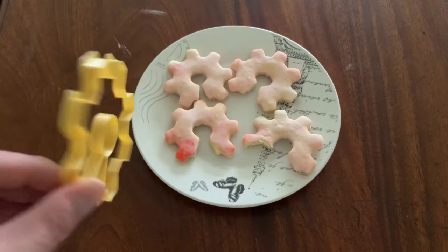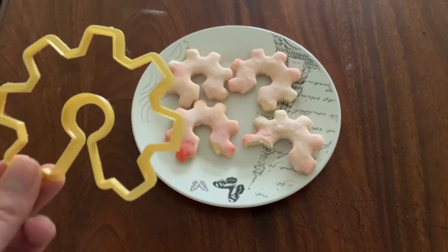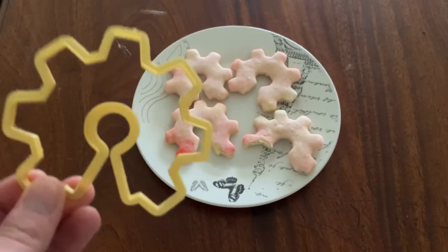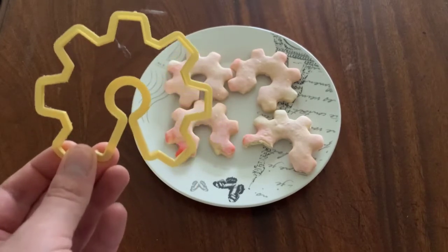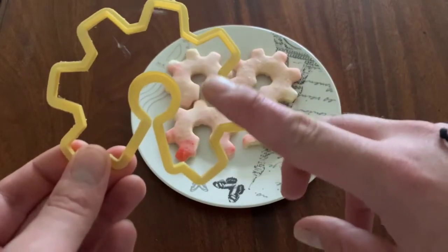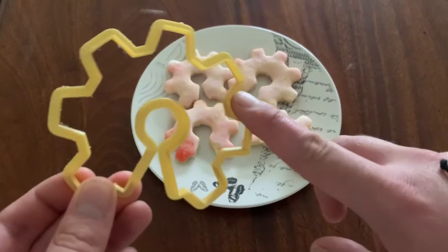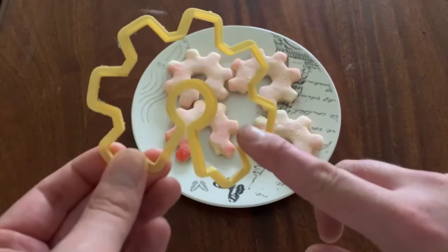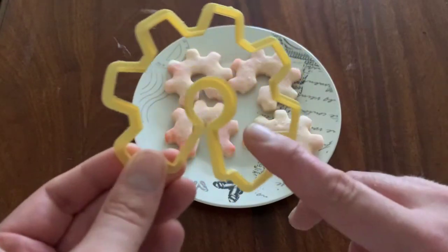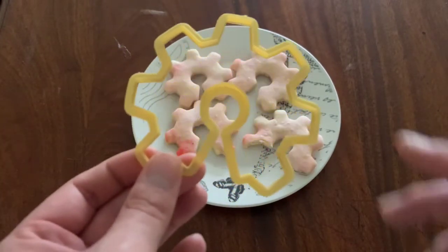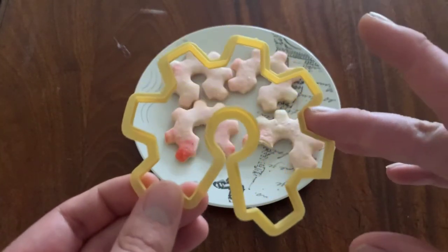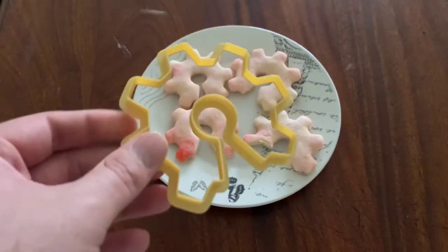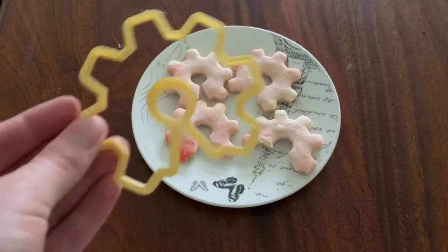Now that you've learned how to, with a 3D printer of course, make your own biscuits, there's a couple things I want to say just at the end. One thing to keep in mind, very importantly, is be mindful with the kind of plastic that you're using. I wouldn't recommend putting any 3D printed plastic into the dishwasher, but if you're using PLA specifically, when you're washing it, keep an eye on the temperatures of the water that you're using to wash it. Anything above 60 degrees will cause it to start to warp and give issues. Even 50 degrees really can start to give issues, so just be mindful.